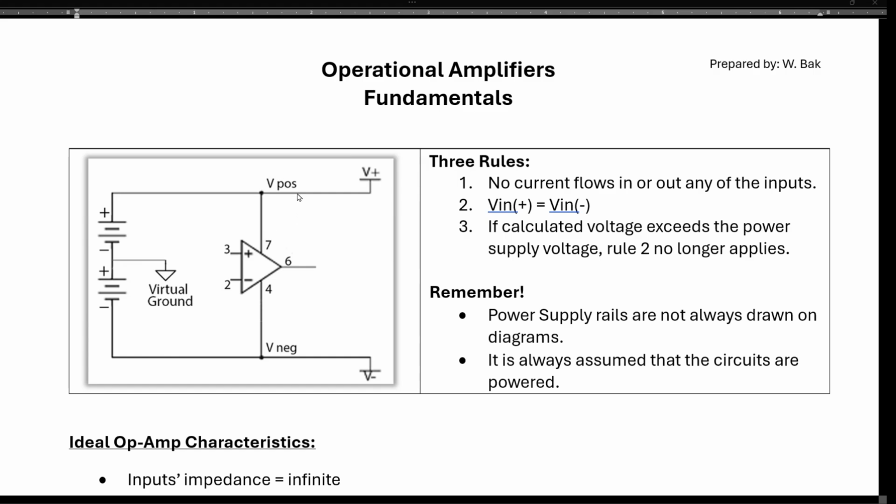So we have plus 15 and minus 15 supply voltage. The gain is 2. And we have accomplished that by choosing the proper values of the resistors that were connected here and there and everywhere. So the gain is 2. And let's say we have 10 volts on the inverting input here. We have 10 volts times the gain of 2 is going to give us negative 20 volts.